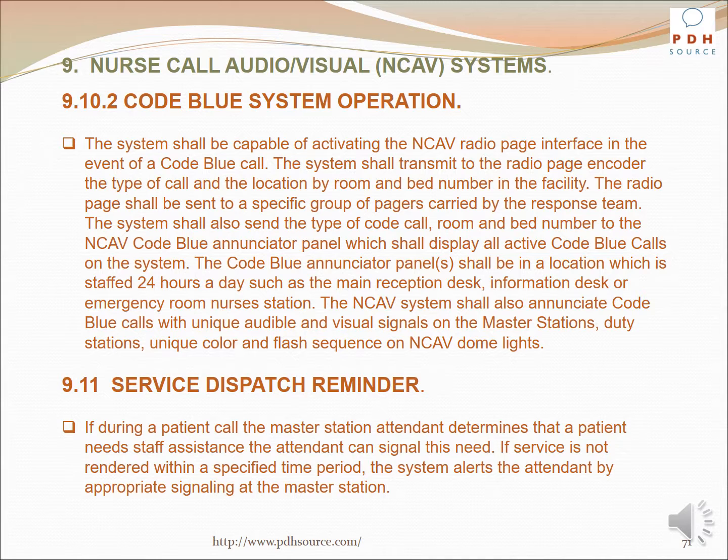The Code Blue Annunciator panels shall be in a location which is staffed 24 hours a day, such as the main reception desk, information desk, or emergency room nurses station. The NCAV system shall also enunciate Code Blue calls with unique audible and visual signals on the master stations, duty stations, and unique color and flash sequence on NCAV dome lights.